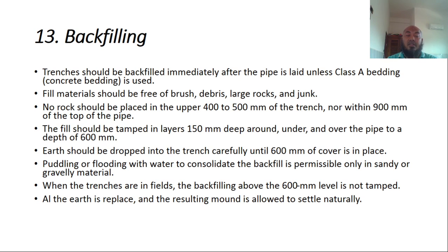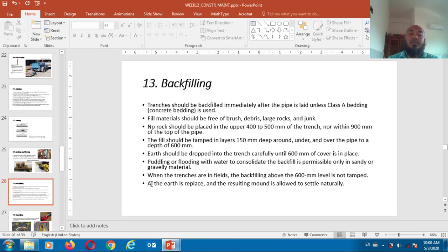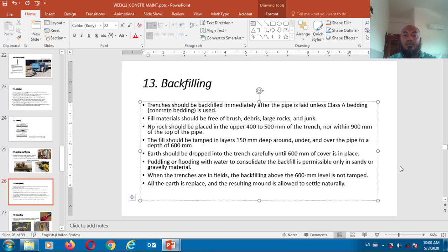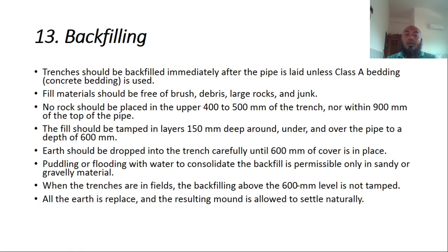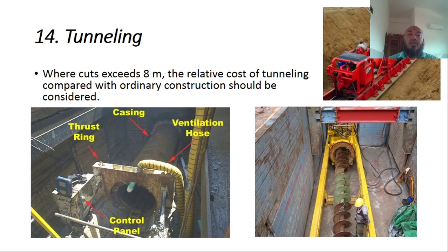When the trenches are in fill, the backfill above the 600 millimeter level is not tamped. All the earth is replaced, and the resulting mound is allowed to settle naturally.